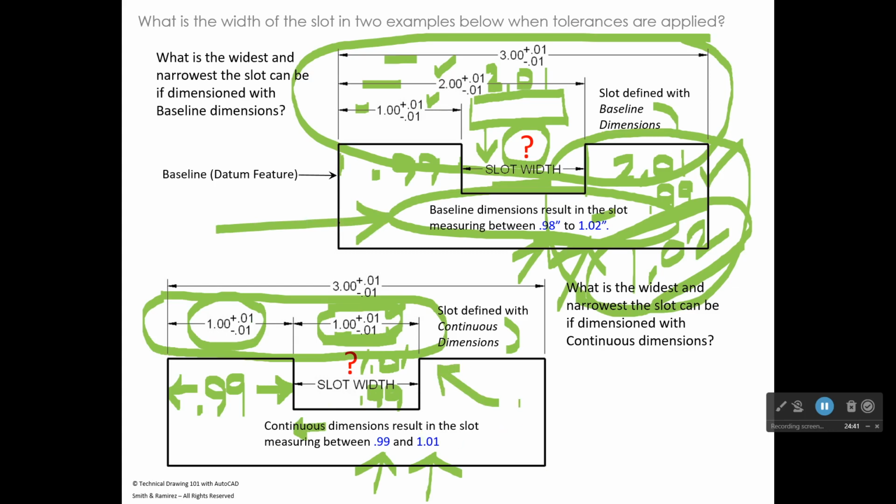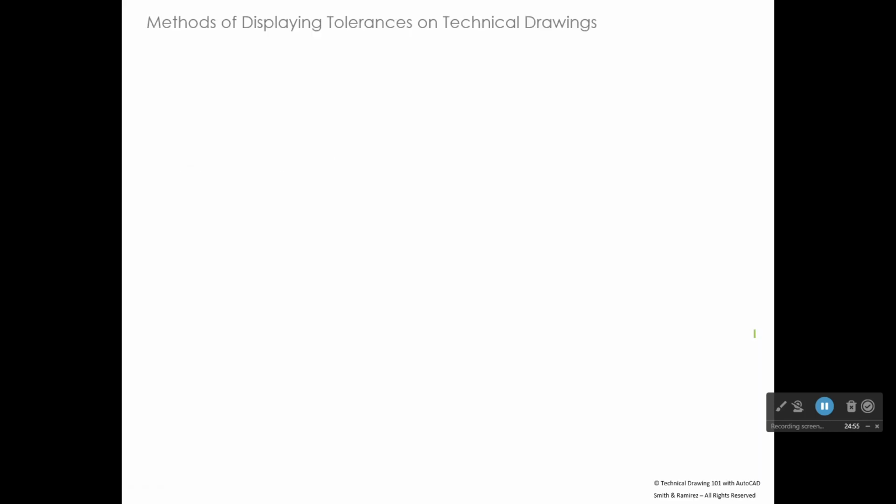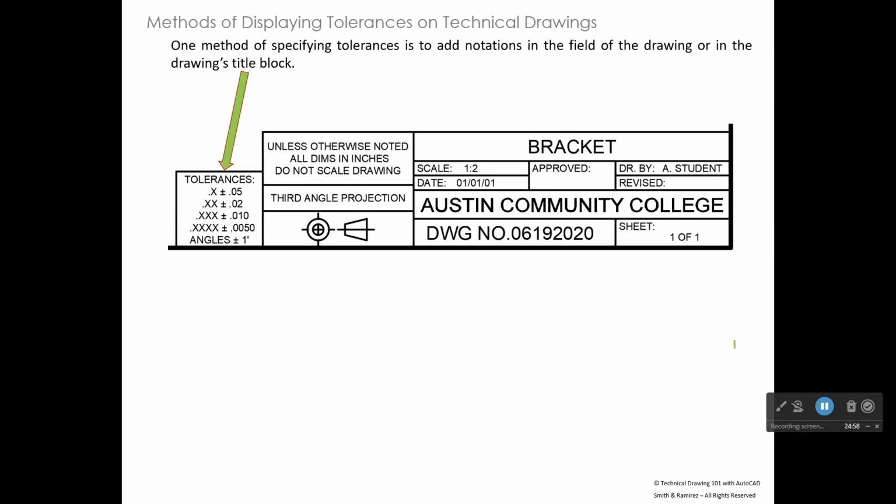Now, as I said earlier, the tighter the tolerance, though, it's possible the part is going to cost more to manufacture. So that's something to consider in the design of parts. The designer's always asking themselves, what's the most tolerance I could give and this part still perform the way we want it to perform. All right, so if you're doing some kind of rough part that's going to go on an oil rig somewhere, you would probably give really loose tolerances, especially if you want things to assemble quickly or come apart quickly. You want to give loose tolerances.